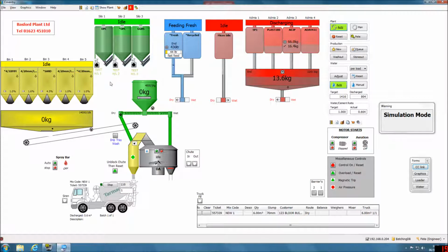So we're now putting the end water, the aggregate and cement's all finished, the conveyor's stopped, it's putting the remaining amount of water in there. And the admix is discharging also with the water. This tells you the detail of the particular water that's going in the truck, that it is the end water. It's split into 3 sections, front, middle and end.